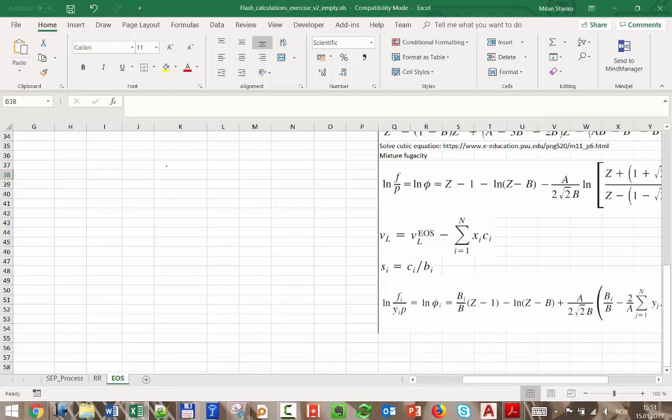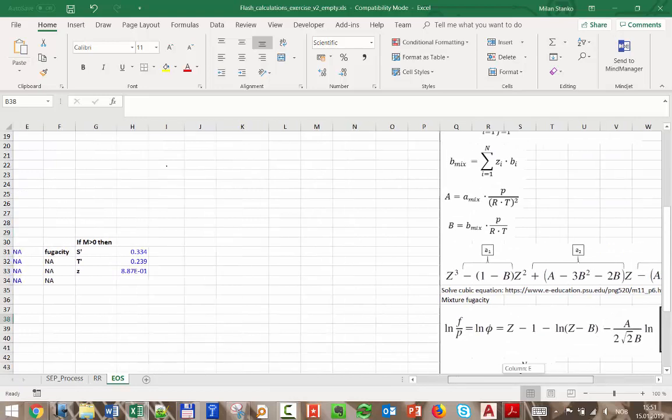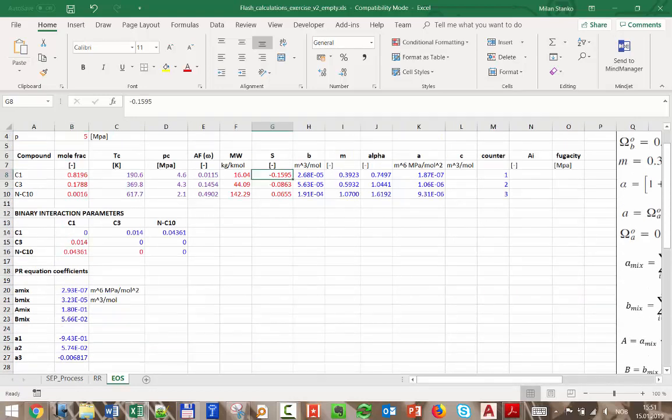Just to recap, this value that we obtained just now is not very good, especially for high pressure, high temperature. So he said let's put in this correction factor, where this is the mole fraction, and this C is the B multiplied by something called a volume shift, S. People were trying to find an S that matched the data they measured in the lab a bit better.